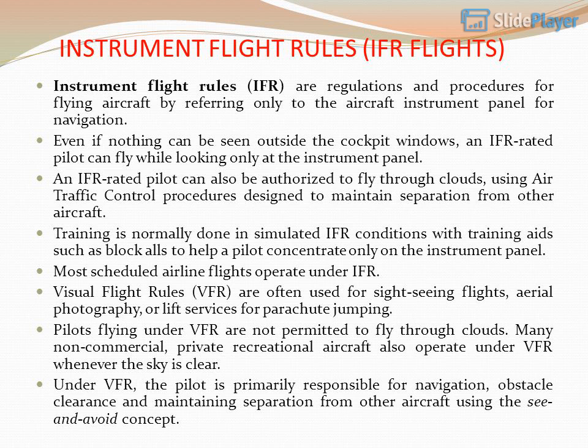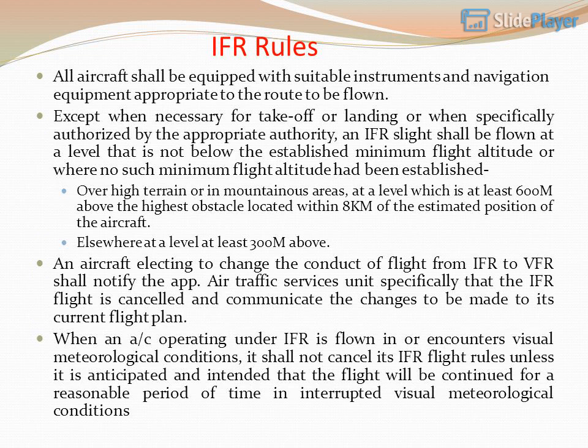Visual Flight Rules, VFR, are often used for sightseeing flights, aerial photography, or lift services for parachute jumping. Pilots flying under VFR are not permitted to fly through clouds. Many non-commercial, private recreational aircraft also operate under VFR whenever the sky is clear. Under VFR, the pilot is primarily responsible for navigation, obstacle clearance and maintaining separation from other aircraft using the see and avoid concept.